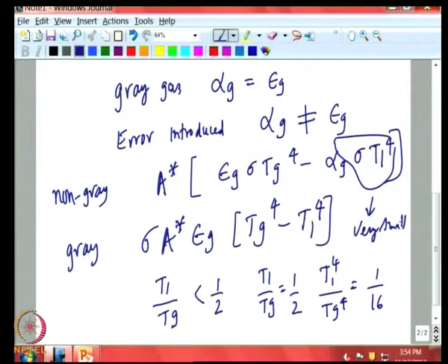So, although our emissivity estimate was quite accurate from the charts, our absorptivity estimates could have been wrong by 50%, but it does not matter, because the second term in the equation contributes less than or around 5% of the first term. So, even if we make a 50% error in the second term, it is not going to fundamentally alter our estimate of the efficiency of the furnace.